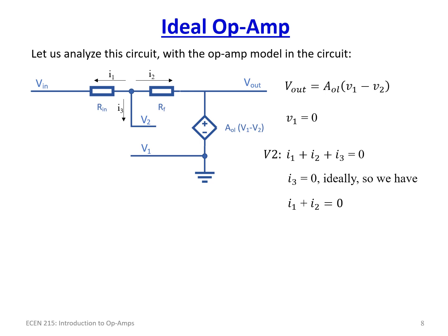Now that we know that, we can actually write the formulas for I1 and I2. Simply put, we have this node here, V2, and we just need to know the current going this direction, which is simply V2 minus Vn over our Rn, and that gives us I1. And I2 here again is V2 minus V out over Rf. So let's go ahead and write those out. Now we're pretty close to having almost everything we need. So we can start combining everything together and see if we can simplify this model. So let's go ahead and do that.